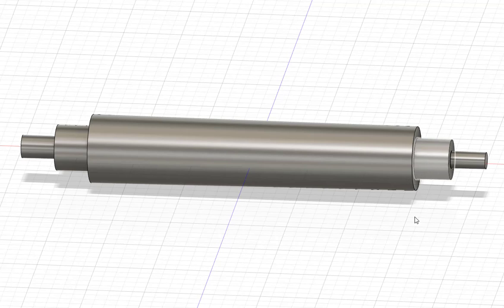The wheels will be on this shoulder, and the load will be pushing up there of equal and opposite magnitude to that exerted by the bearings. And that exposes the center section of the shaft to a pure bending moment.